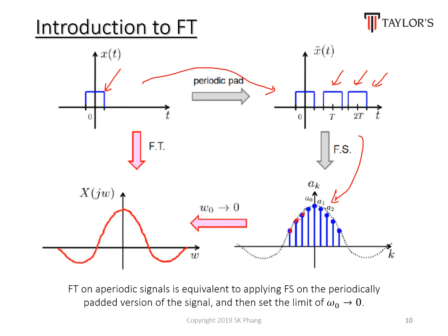Remember, the Fourier series are all the spikes. Now we just need to connect all the spikes together, like the dotted line here. After we connect them, this becomes the Fourier transform of that signal that is not periodic. So I repeat, this is the Fourier transform of a signal that is not periodic. We can do it that way.